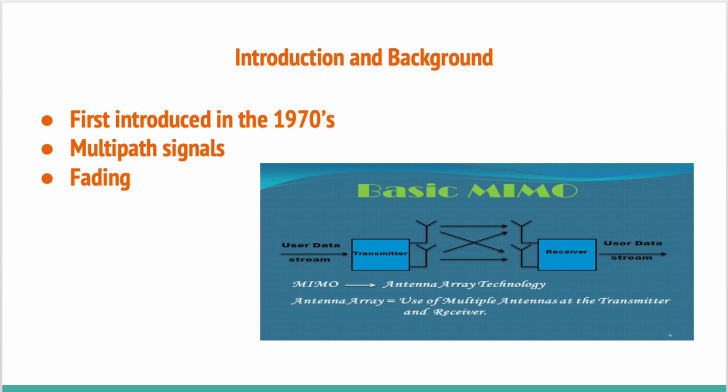Space-time block code, also known as the Alamouti code, was developed by Siavash Alamouti and is widely used in MIMO-OFDM systems. Alamouti's 1998 paper showed that the benefits of receive diversity can also be achieved using a combination of transmit diversity and space-time block codes. A key advantage of transmit diversity is that it does not require multiple antennas and RF chains in handsets.